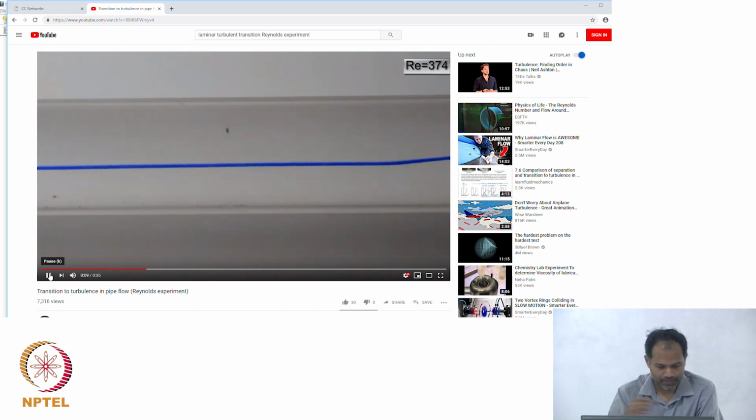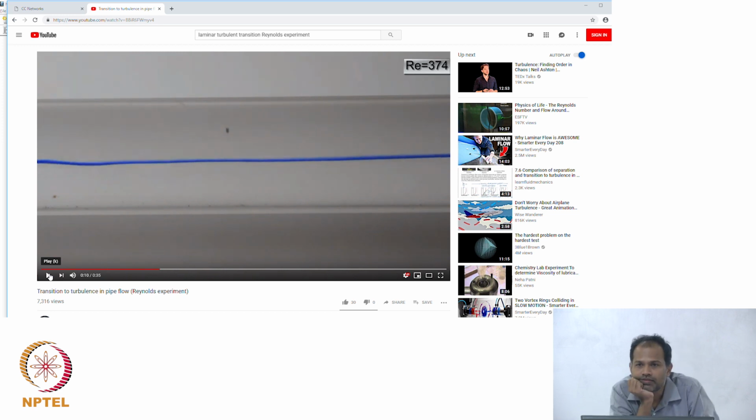It doesn't look like a pipe because the Reynolds number seems to be very small. Diffusion will happen, but over a very large time scale, because diffusion is a very slow process. If there was no fluid flow, you would have seen the ink getting diffused, but you are not letting that happen.